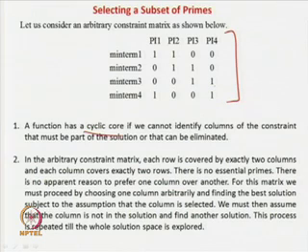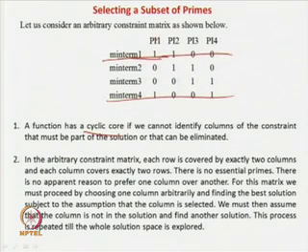So in this case there are a lot of choices, and you cannot directly reduce the matrix. You see it is 1 1, 1 1, 1 1 and 1 1. So this is a cycle: this 2, then this 2, then this 2, then again it cycles. This is called a cyclic matrix, because there are a lot of choices. You can say I will take P1. If you take P1, this term is covered and this term is covered. If you take P1, the remaining are these two. Now you can take P3, then again this one will be covered and this will be covered.